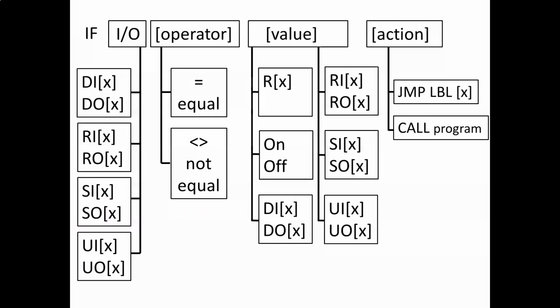So thinking back to what we talked about for the if statements: if you're using an I/O, digital I/O, robot I/O, system I/O, user I/O, standard I/O, equal to, again, sometimes you can have inputs on this side to do something. So again, the if statement can use I/O in it as well.